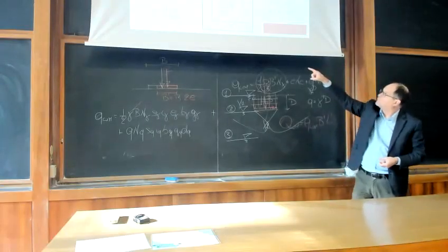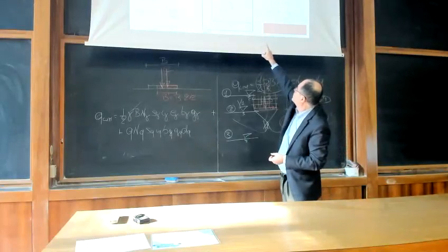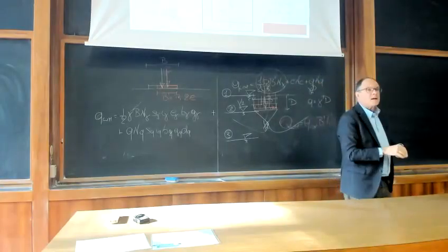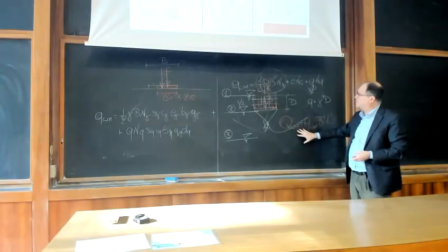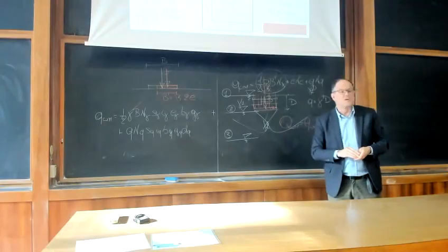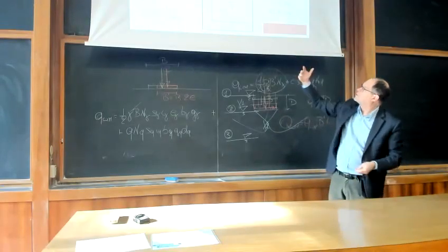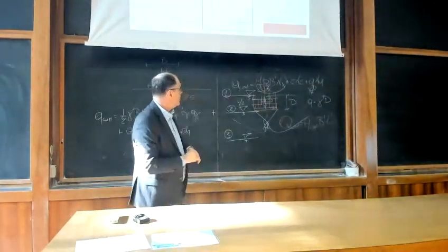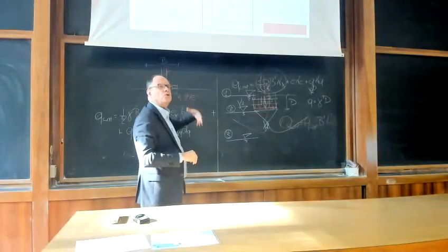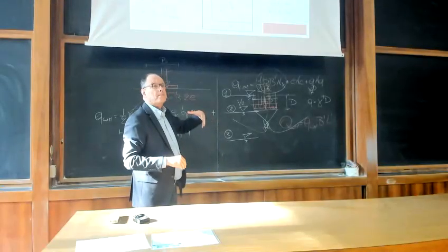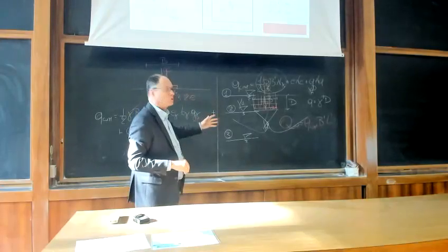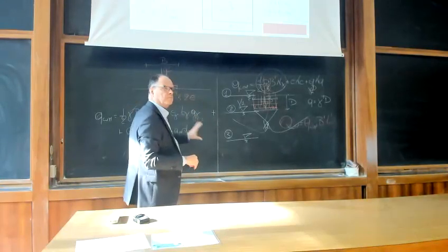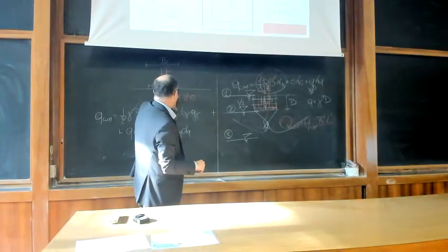So you end up with a footing, which is included by the dashed lines, where the load is centered and with a reduced limit pressure provided by this reduced size. So the Meyerhof suggestion, referred to as the effective breadth, is quite a clever way of not introducing further empirical factors, but it is the only one among all this list of factors that acts this way.